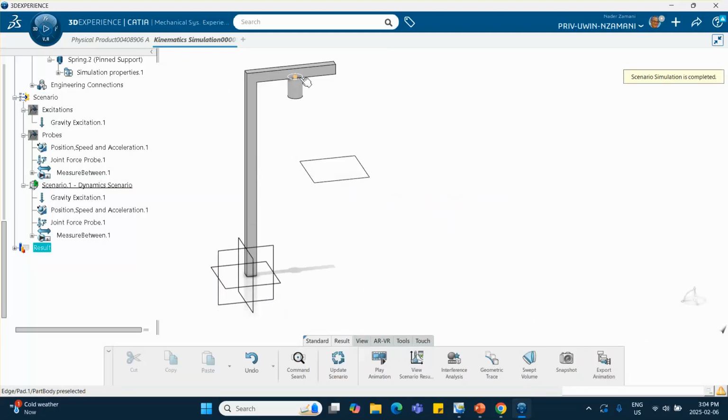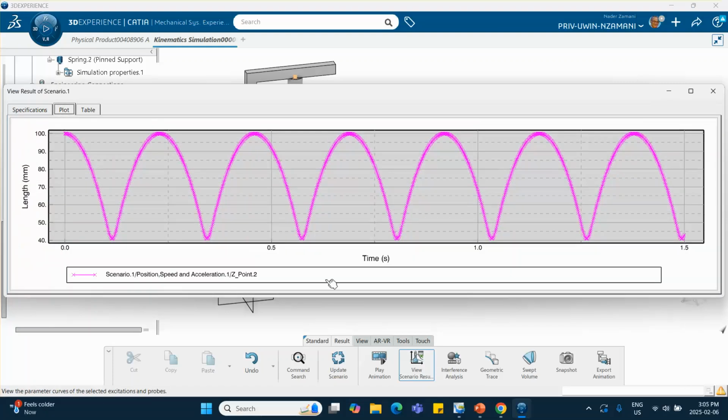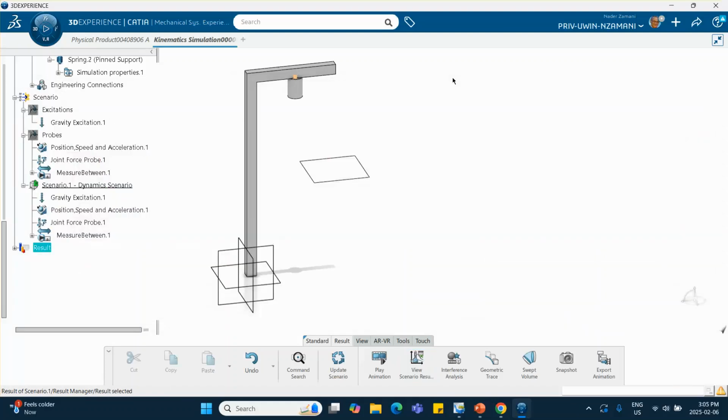And it really doesn't matter whether you do the distance or you do the plot. Now, if you go here and say, okay, show me, everything takes longer because there's more results to retrieve. Just give it a second. Okay, so deselect everything. And if you look at the Z, yeah, looks a lot better. This goes 1.5. The plot that I gave you was over 1 second. Now, notice that there is no damping here. The heights are all the same.